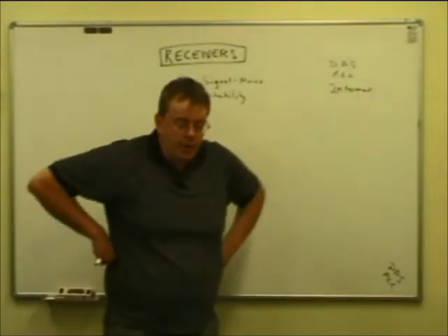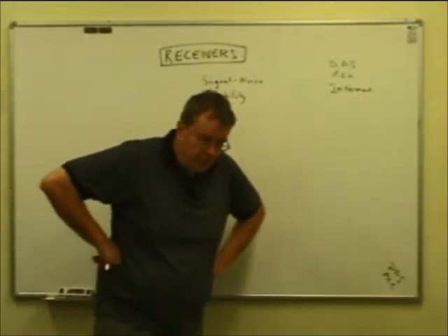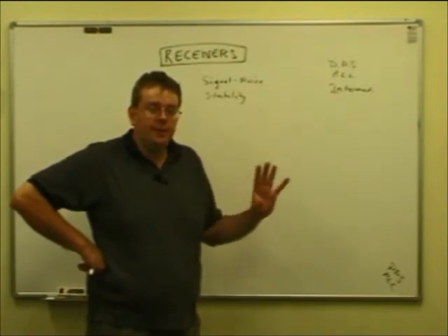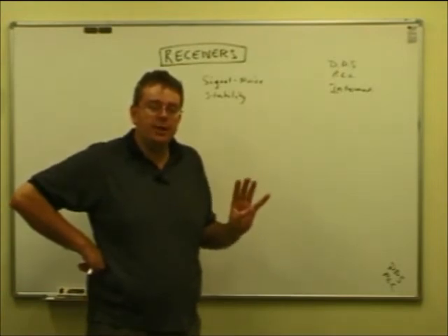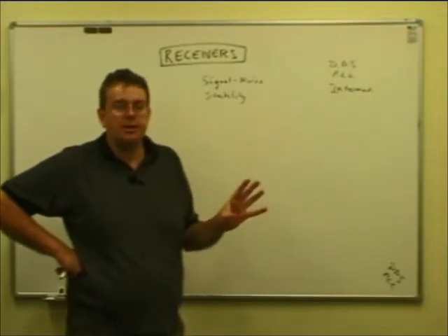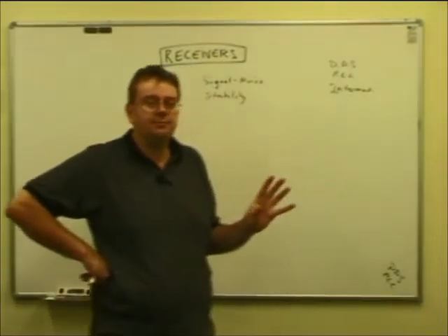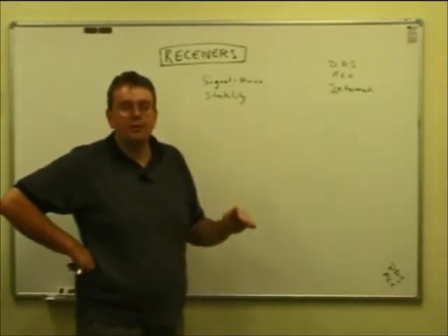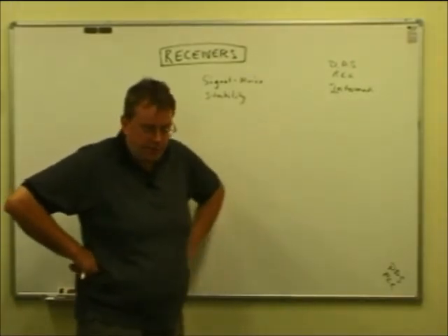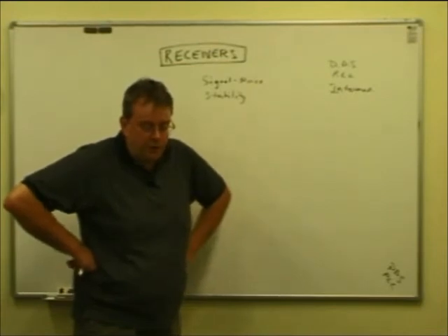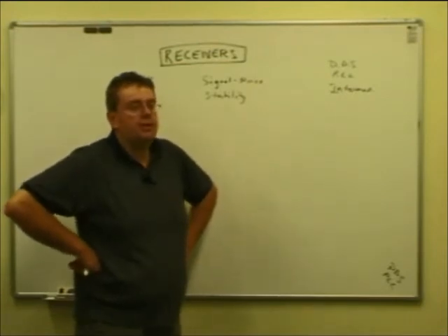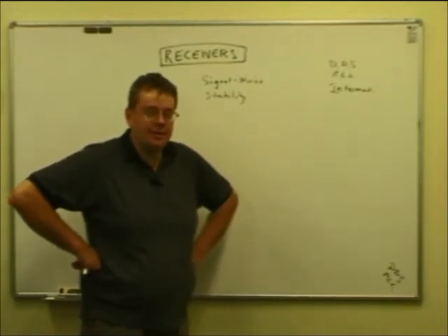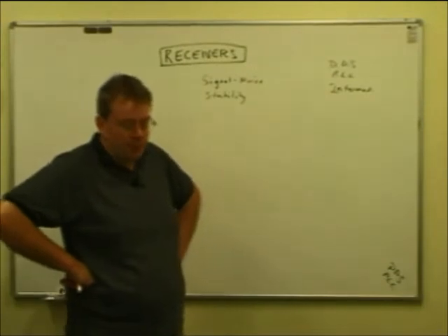When we're listening to a single sideband conversation, if our local oscillator shifts up or down in frequency a little bit, then the pitch of our received signal will change, and we'll do a demonstration hopefully in another session, watching a receiver in action. You'll hear the pitch going up and down as the local oscillator drifts. So that's often nowadays what we refer to as stability in a receiver, is a local oscillator staying where it's put. What you tune it to, it will stay there and won't move in frequency.